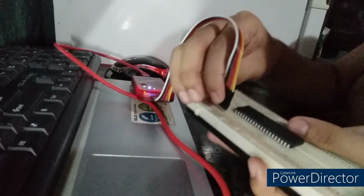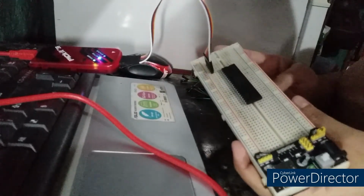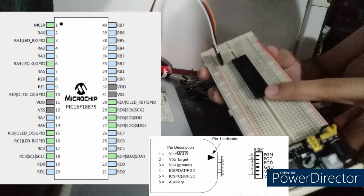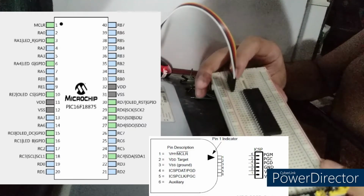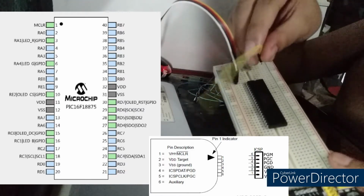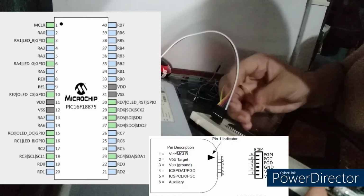Okay, so that's our first connection. Now, for your convenience, I will show you the pin configuration of our PIC16F18875 IC here on the screen. We will be connecting pin number 1 of our PICkit 3, this yellow wire here. We will be using our connecting wires. So we will connect pin number 1 of the PICkit 3 to pin number 1 of our IC.